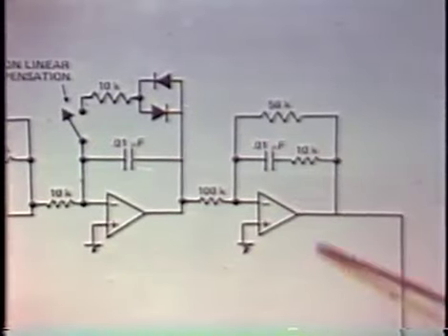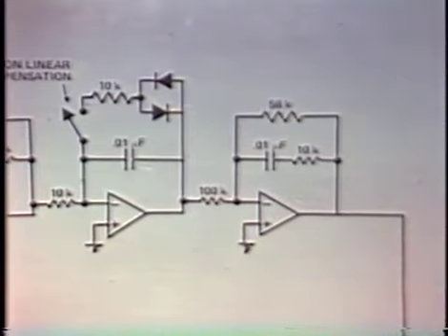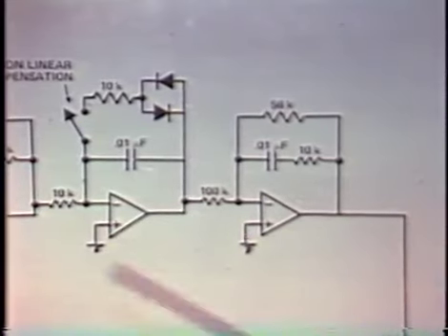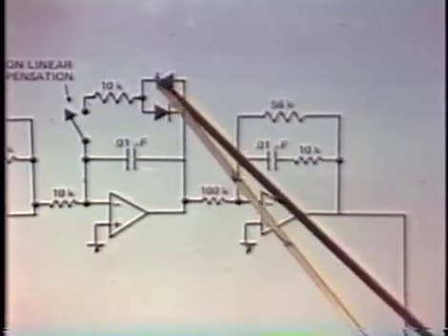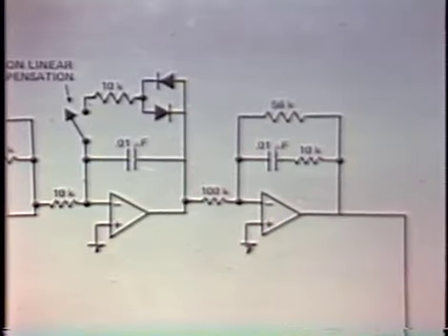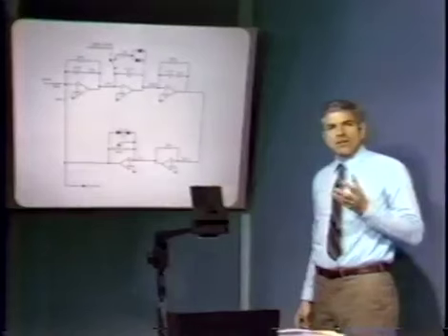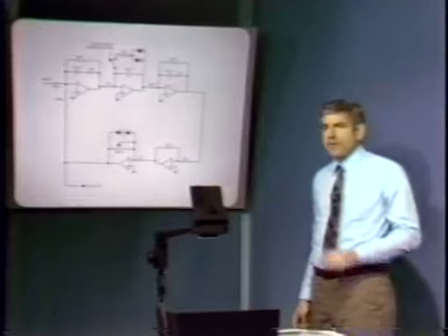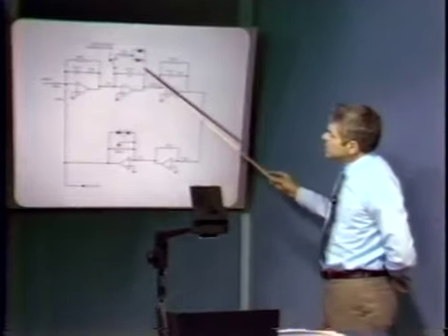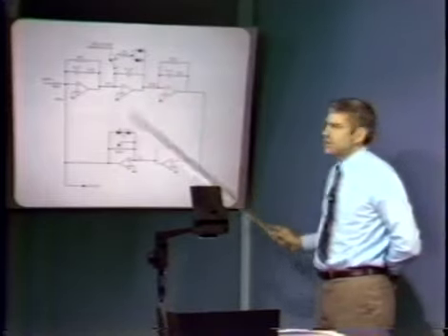If you go back through the gains of these elements, you find that as long as the system's in its linear region, the signal level at this point is quite small. It's less than a diode drop, less than the forward drop of a diode. However, when the system pops into the mode where it's oscillating at the low frequency as predicted by our describing function analysis, the signal at this point becomes quite large. It becomes significantly larger than 0.6 of a volt.